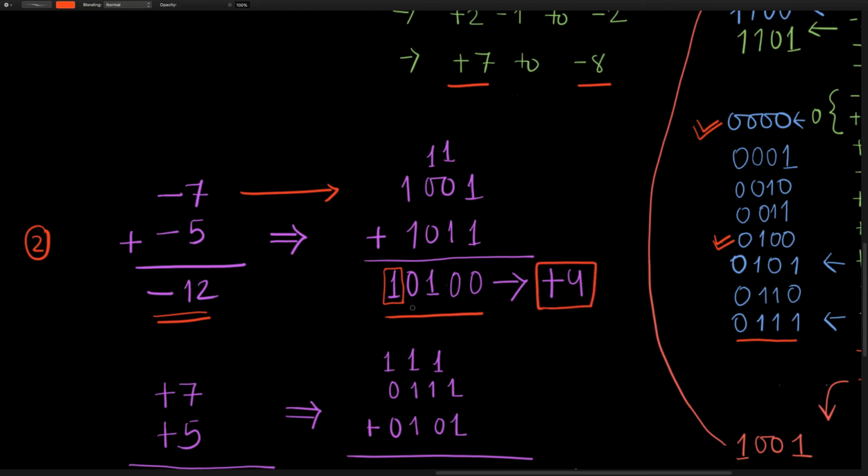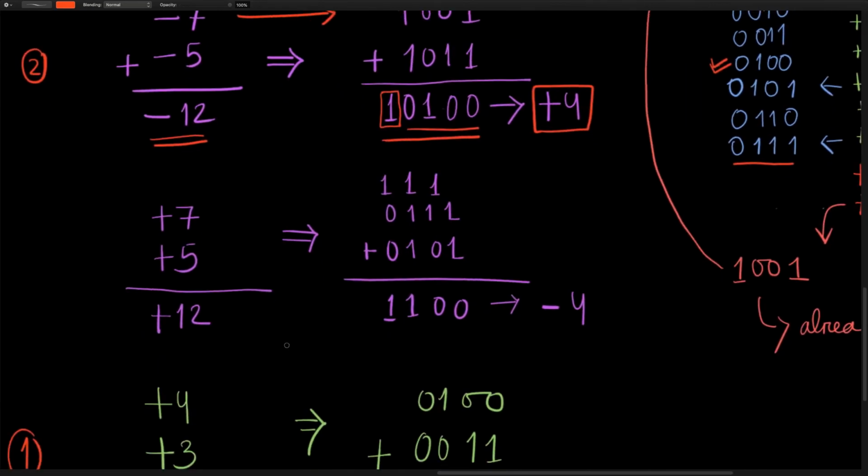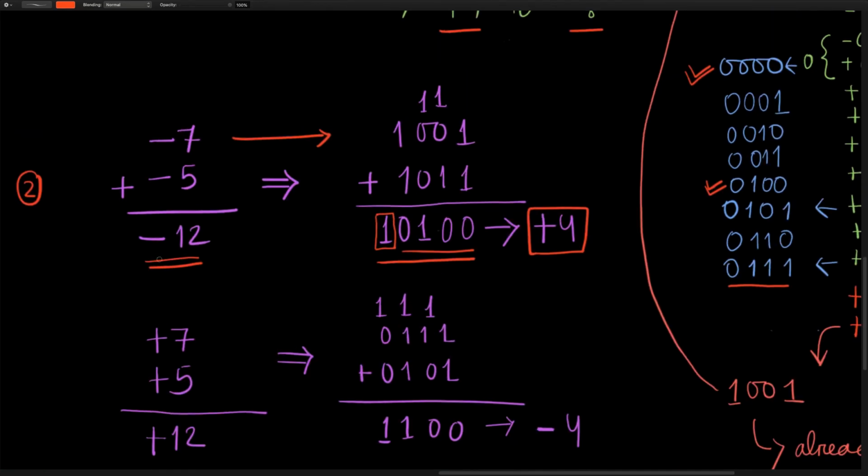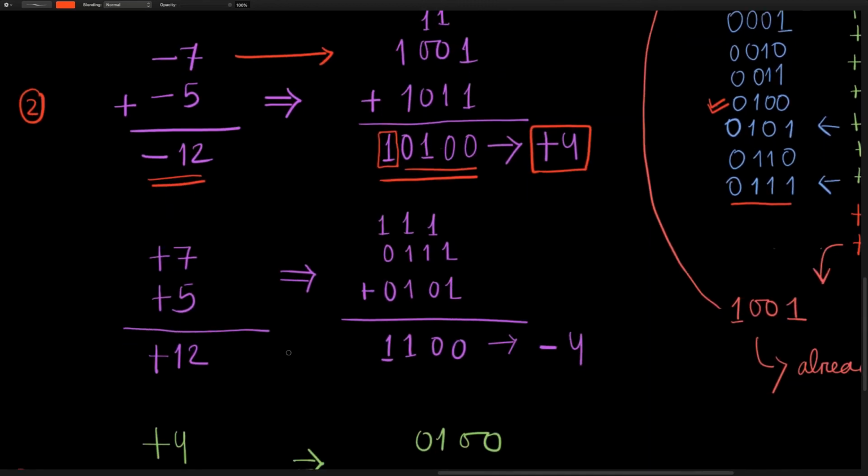If you look at the solution, and you have followed the signed binary number notion, you will consider that the first number would be positive, but that is not the case. The answer should be negative 12, and this problem arises because the answer we are getting is not within the range with which we can represent the numbers with 4 bits.